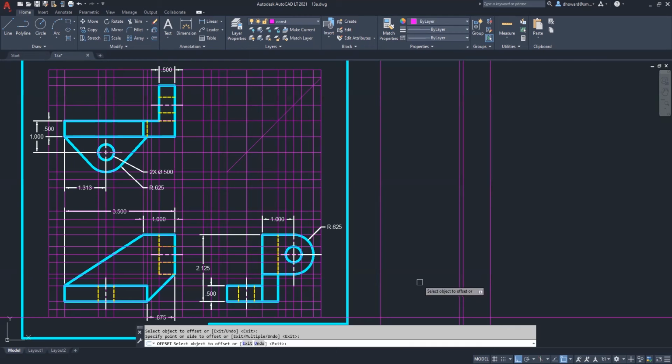And if you look on the drawing, it says that is 1 5/16. So this line is going to be offset 1 5/16 over to the right. And I'll do that now. Enter to get out, enter to get back in. And instead of typing 1 5/16, I am going to type 21/16 because you have to use an improper fraction in AutoCAD. Of course, you could have just typed the decimal value, which you can see over here is 1.313. That's the one we just did.